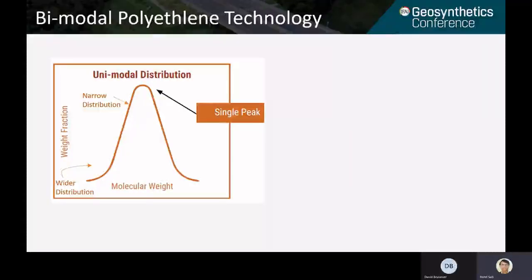So you can have average tensile properties, average long-term endurance properties. Now, if you try to narrow it further, you'll actually get a stiff, higher tensile material, but then you will have difficulty extruding the material. You may also have difficulty achieving some of the long-term endurance properties. Now, if you try to widen and shorten the curve, it could be a supple, soft material, but then you are compromising on other properties like strength.